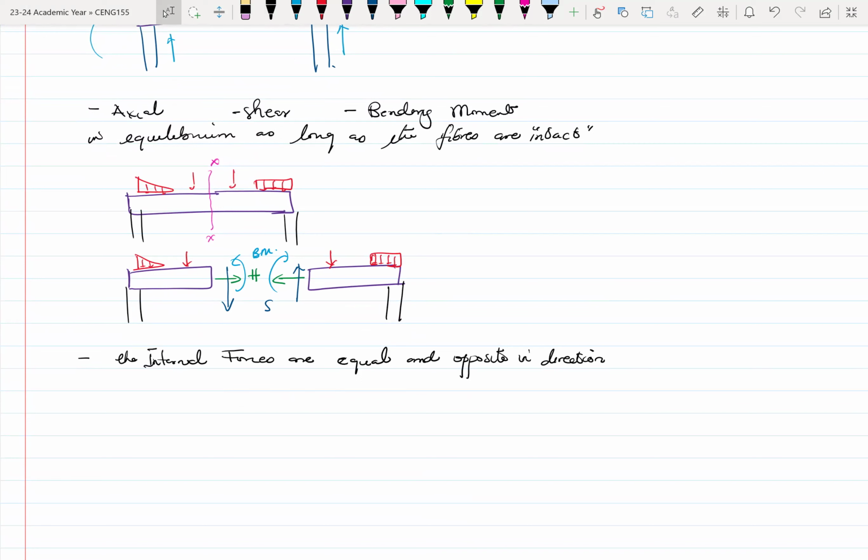And again, when we are defining the structure, we did mention that the structure should transmit loads, right? And also, in doing so, it should not collapse, and it shouldn't deform excessively. So if your supports are very strong, they have good reactions against the loads. But if the beam, which is supposed to transfer the external load to create an external reaction, is not strong enough, then that will collapse. Or it can deform excessively.